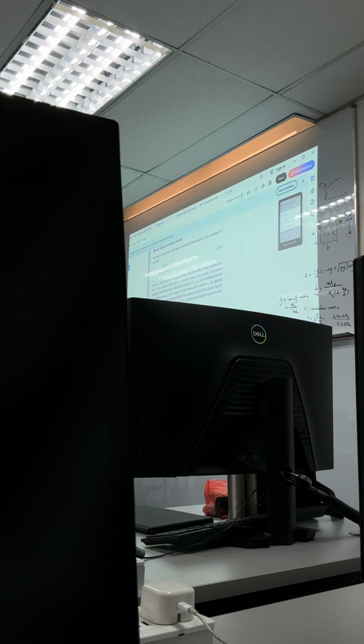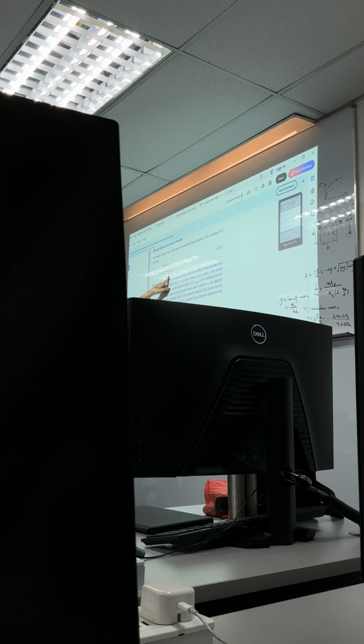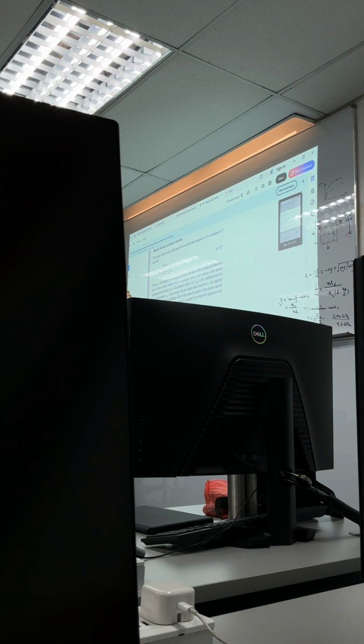Right? So this equation is w max, the crack width, is equal to 3 a_cr ε_m divided by 1 plus 2 bracket (a_cr minus c_min) divided by (h minus x). Alright, there are so many symbols there, which you also don't know what they mean, right?